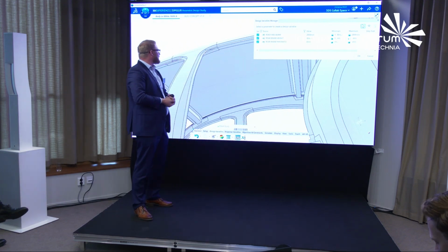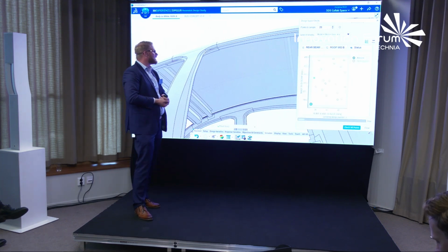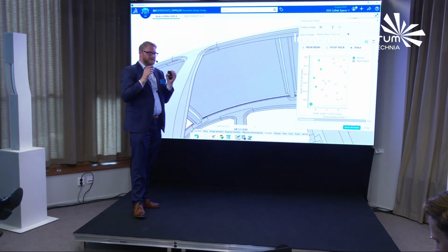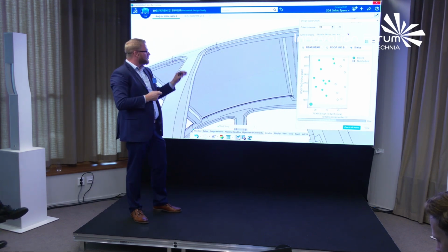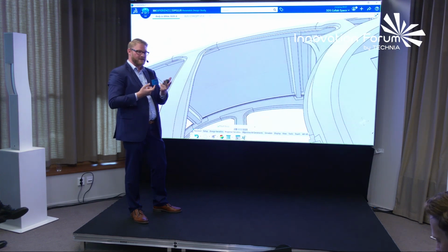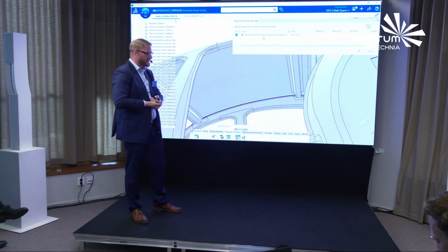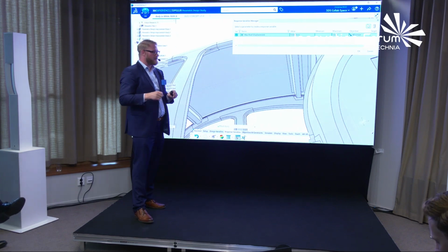We're reading in the parameters, we're unlocking them, and now what we're doing is in the end a model check. So all the different design parameters, we're not solving the simulation because that's time consuming, that's cost. But we're just checking: is my geometric model updating, is the mesh working, is my scenario definition working? Just a pre-check. And once we figure out, yes, it's all robust, it's working, we can now go ahead and